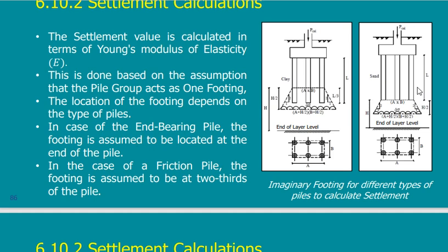I take the shorter direction, multiply it by 2. This will give me the end of the layer that I can consider in my analysis, and it will be a very good approximation, because my load is supposed to reach below till a certain level. Below it, the stress will be less than 0.1% of the load. So I can ignore what is below and use this.